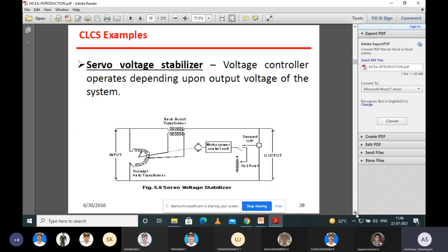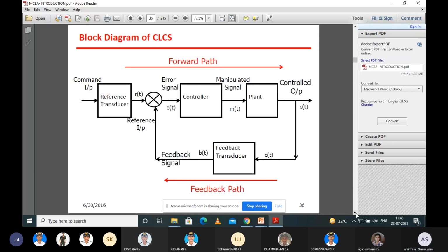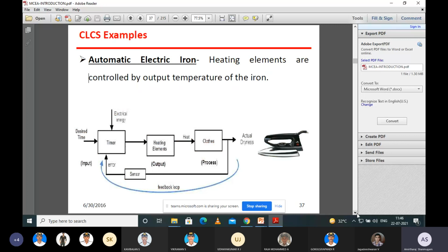The electronic components are stable only if the voltage is between the mentioned levels. So we need to maintain the voltage with the help of this stabilizer. If the voltage is increasing, we need to drop some voltage. If the voltage is decreasing, we need to increase some voltage. Nowadays, this is done with the help of components like the zener diode and series voltage regulator. With the help of transistors, it is also possible to design more regulators. Okay.